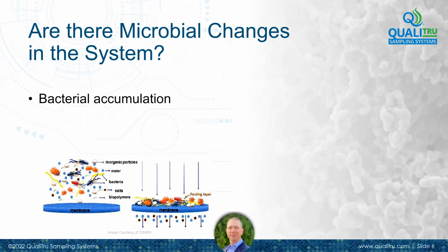Usually, the run will take longer, which means the CIP window gets tighter, gets pinched towards the end of the day, and maybe it barely passes. And really, this is an ongoing effect day to day where foulings are pounded in and it makes the next run even harder. Second, operating temperature.